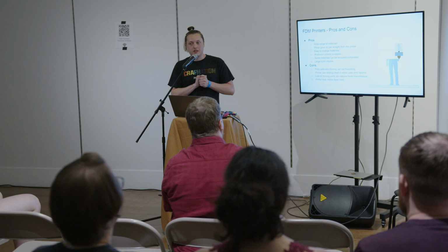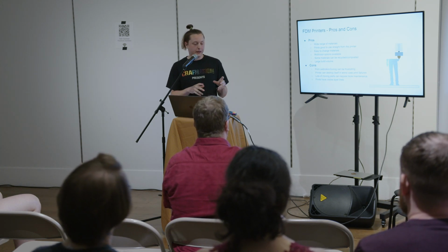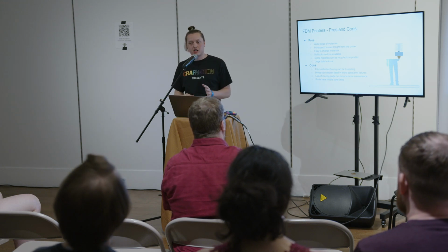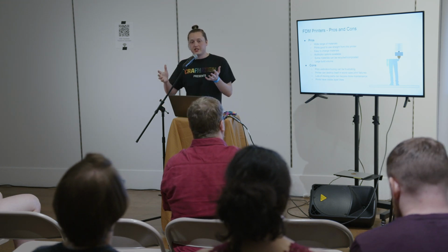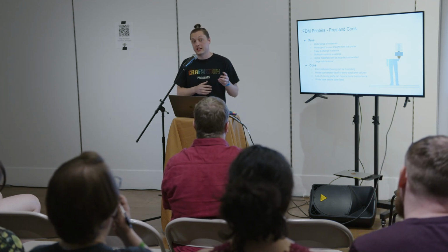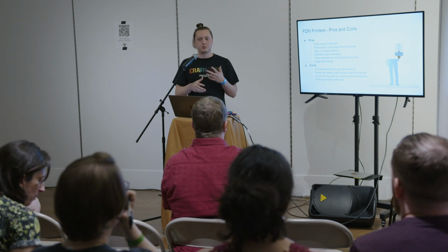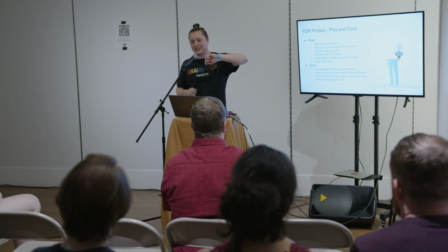Yeah, and then pros and cons for FDM style printing. There is a huge range of materials, tons of colors, all sorts of options. As soon as it's done printing, you just get to take the print off and use it, which is very different from resin, where you have this whole washing and curing post-processing that you have to do. It's pretty easy to change materials because even on printers that don't have some kind of automatic filament changing, it usually only takes a minute or two, and it's basically just take it out and put a new one in.